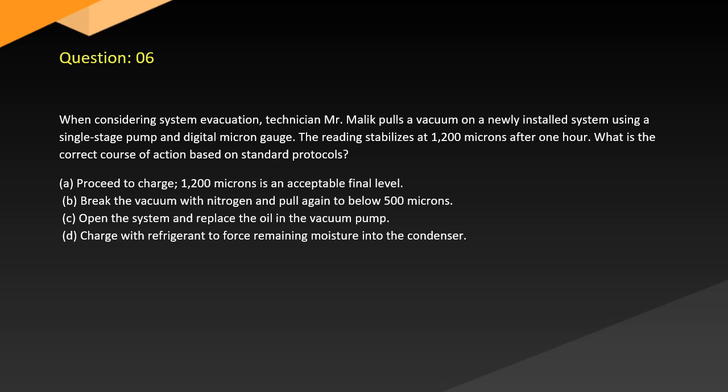A. Proceed to charge. At 1200 microns is an acceptable final level. B. Break the vacuum with nitrogen and pull again to below 500 microns. C. Open the system and replace the oil in the vacuum pump. D. Charge with refrigerant to force remaining moisture into the condenser.